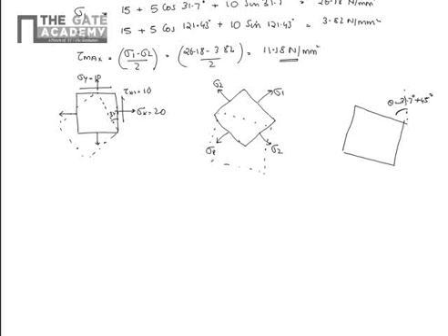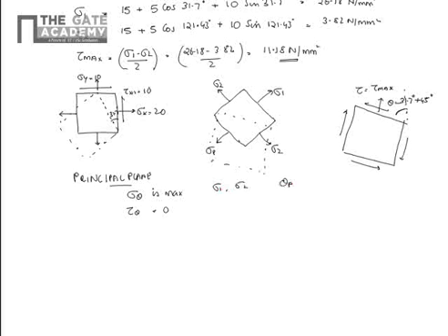If I take this plane, I will have my shear stress as the maximum shear stress. The tau will be equal to tau max. But what will be the sigma acting here? The very important characteristic of the principal plane is that on the principal plane, the normal stress is maximum and shear stress is 0. Normal stress maximum is given by sigma 1, sigma 2. And the plane on which it is given by theta p1 and theta p2.